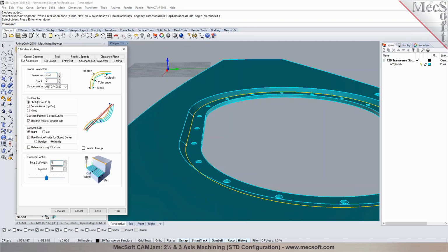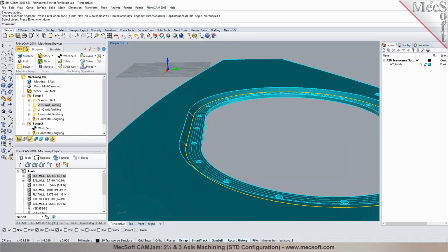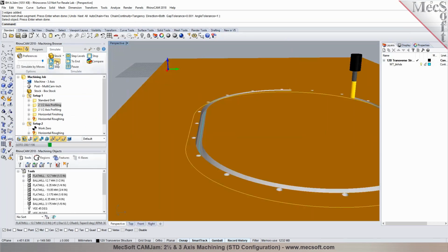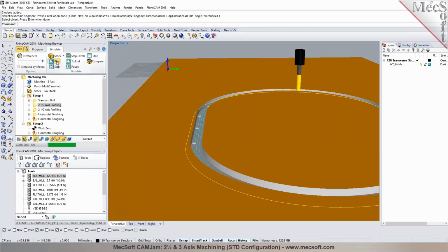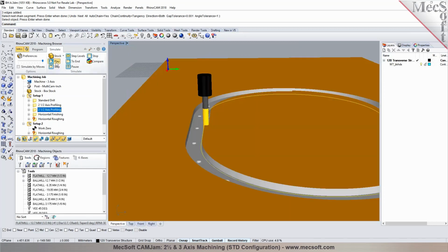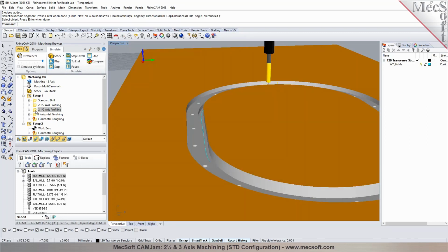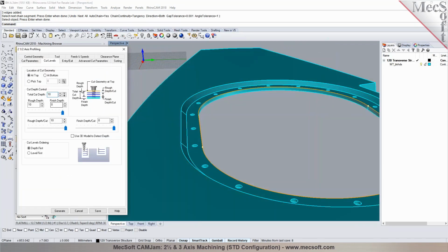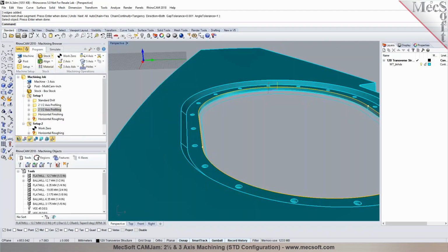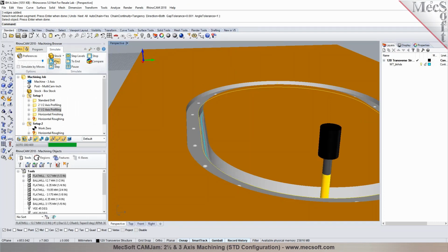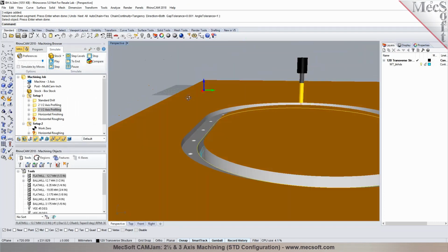When you say at the bottom, it picks the bottom of the surface. It doesn't pick the bottom of the stock. Well, it's the bottom of the surface, the geometry you selected, right? That's the floor. Great. Okay, so now you're basically relieving this material out first. And then you're doing the next profile in here. Yeah. If you wanted that to go deeper, you can change the depth to, let's say, 20 millimeters or 15 millimeters, whatever that needs to be. So you have all of the control that you need in here for programming it.